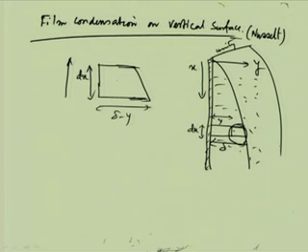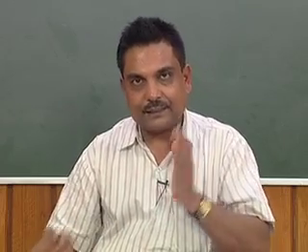What is happening here is that there are forces acting on this fluid element, which is the condensate, a liquid material. One force acts upward, the drag force, which is a viscous drag, and this is mu into del Vx by del y into dx. As I told you, dx into the unity width gives the surface area, and this drag force is acting on that surface.